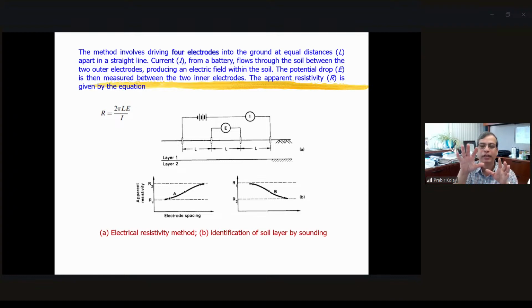If you have more confidence in your bore log, then you can design your foundation or any structures more economically. Most of the time in geotechnical engineering, if you don't have confidence in your data, use more factor of safety. Geotechnical engineers generally use more factor of safety when they don't have much confidence in their geotechnical data. It may not be economical, but in most cases with geotechnical structures, we don't want any failure. If it fails, then it is a problem, right? There are methods to rectify these days, but much more expensive.